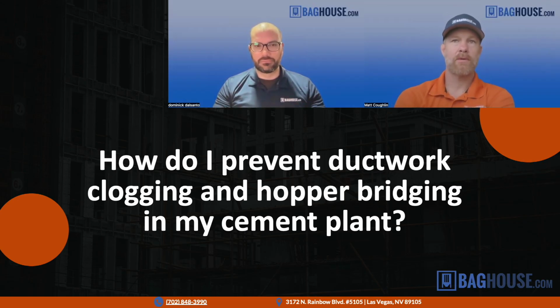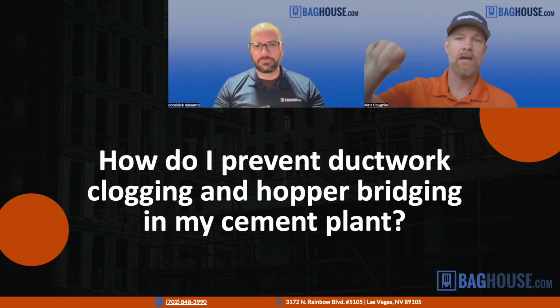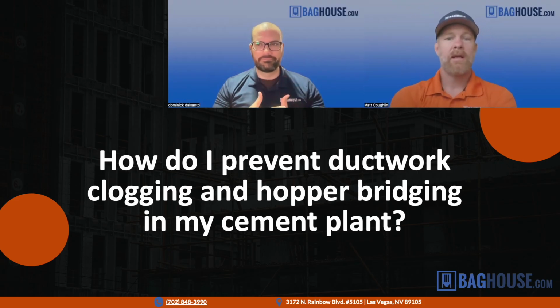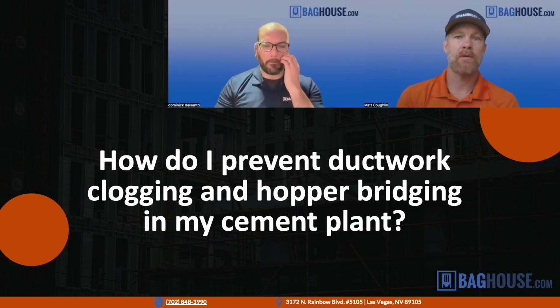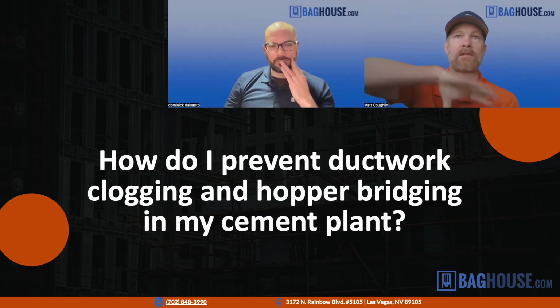Talking about the ductwork, since we're talking cement applications, one thing that's pretty common in like crushing, part of the process in particular, you'll see a lot of cement plants have this grasshopper leg style ductwork. And that's pretty common. And the idea there is to basically ensure that the heavier stuff that gets pulled off your conveyor hood falls back into the process while the lighter dust goes up into your ductwork. So you want to make sure that the ductwork itself is sized properly to keep the lighter stuff flowing.